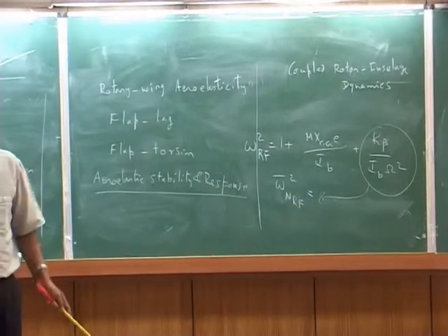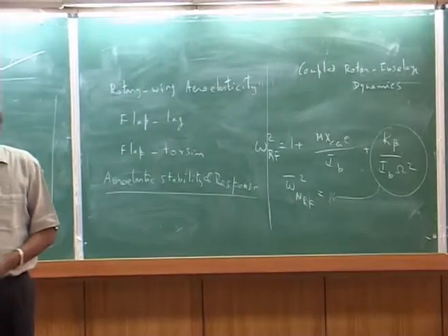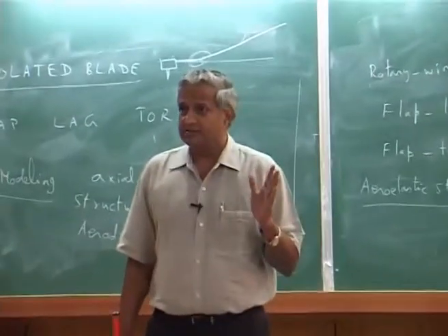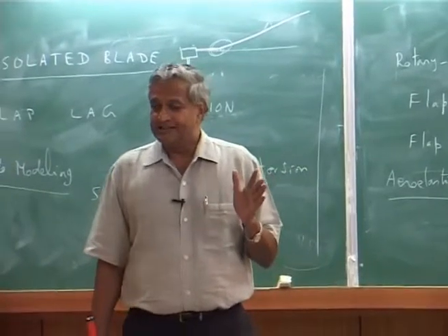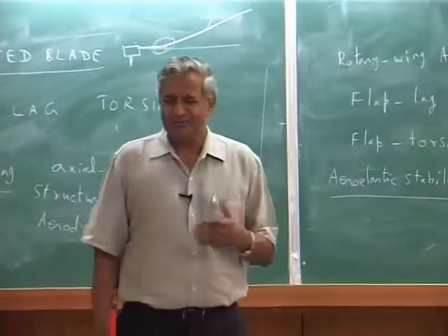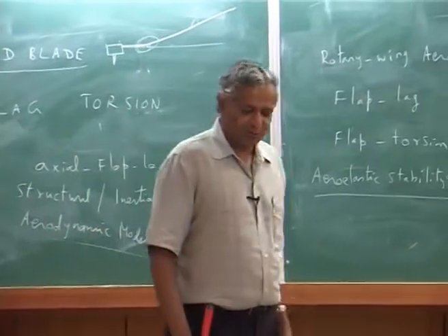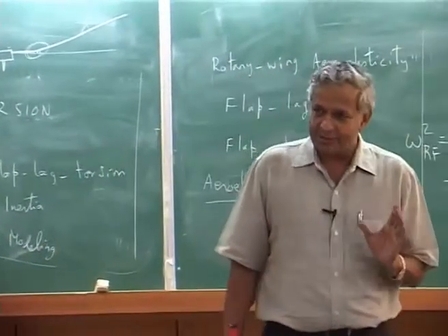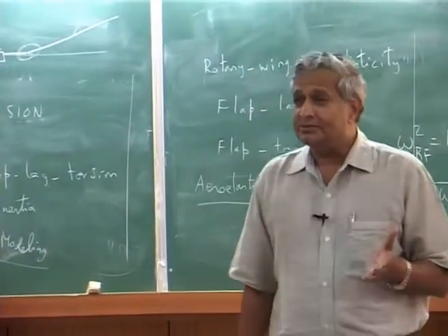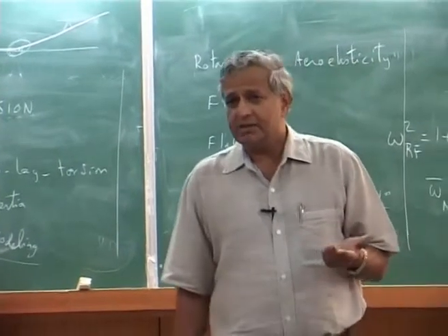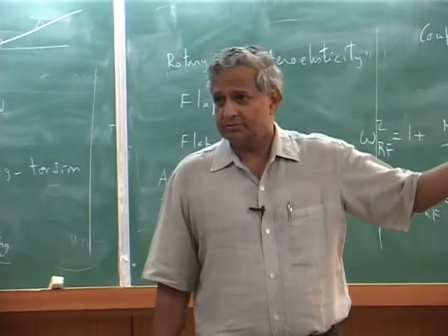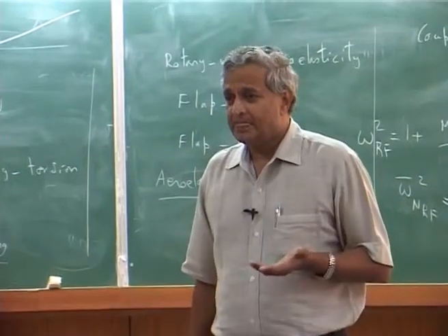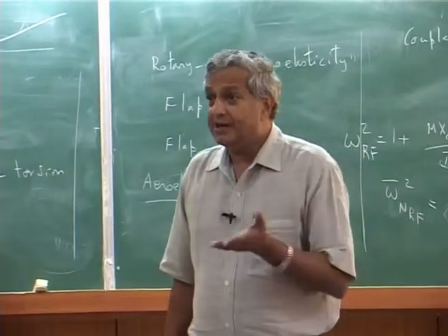But in this case the root is going to bear the brunt of the load. Always, everywhere, the root only takes. Otherwise, the blade middle point and all, no. Root only has all the loads. See, one is the centrifugal load. Centrifugal load is of the order of 100,000 Newton. Phenomenally large. But the flap load will not be large.